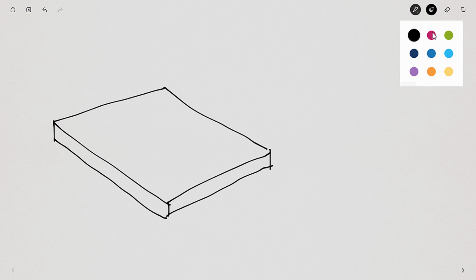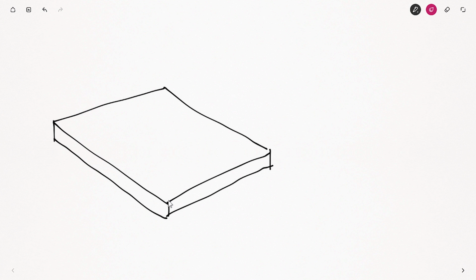Let's start the design in ARCHICAD by creating a slab. Later, we'll connect this slab with Grasshopper using the coordinates of 3 vertexes of the slabs, represented by the purple circles in the sketch. These 3 vertexes define the plane of the roof where we will add the solar panels. By connecting these vertexes, we can define a local coordinate system indicated in the sketch by the blue arrows. The vertexes with the coordinates define that area of the roof where we want to distribute the solar panels.